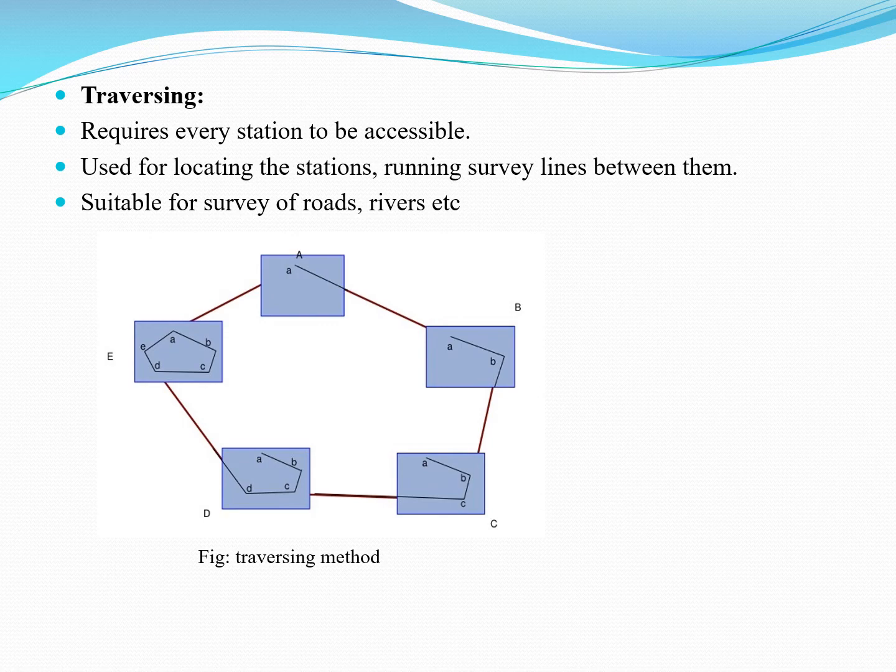After that, the alidade touching point a, ranging rod at B is bisected and the ray is drawn along the alidade, and distance AB is measured and plotted on the sheet by taking any suitable scale, and the obtained point is marked as small b. Okay, so the table is shifted. Now the table is shifted and set over station B.